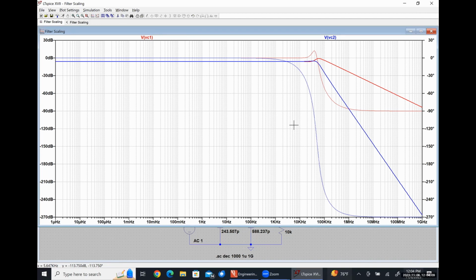So looking at this system, we can see that the voltage drop across our second capacitor never gets even to 0 decibels, meaning that it's never going to have even 1 volt across it. Right? So we are at slightly above -6 dB here because of the resonance, but it's not a huge amount by any stretch of the imagination. So we don't even put 1 volt across it. So that's probably going to be pretty safe. Over here, we have an output voltage that is about 0 decibels. So it's very close to 1 volt, but still not enough to warrant anything.